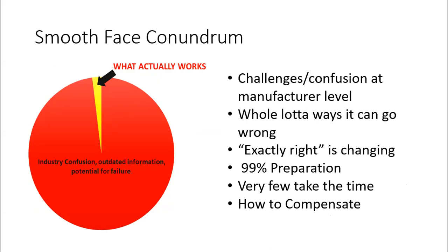The problem with that is it creates a tremendous amount of confusion, okay? We're seeing, especially since 2012, that people are not used to having to prep it as much. Again, before 2012, we could almost get away with murder because high penetration oil-based stains will penetrate an unsanded face enough that it's going to work 80% of the time. The 20% it doesn't, you just refinish. It's not a big deal. But now there's a whole lot of ways it can go wrong. And exactly right is changing.